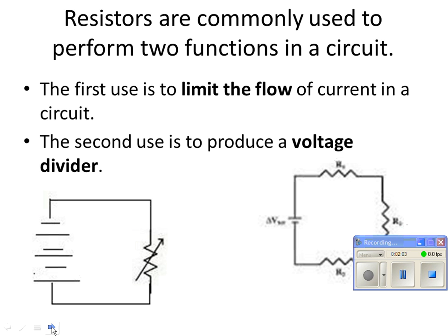E equals I R, right? E divided by R. So 12 divided by 1 is 12 amps, right? Now let's turn it all the way up to 500. Get out your calculator. I know this is going to be very difficult. 12 divided by 500. It's going to be way less than 1, right? So as we've dialed this variable resistor up from 0 to 500 ohms, we went from 1 ohm resistance, and we flowed 12 amps of current.